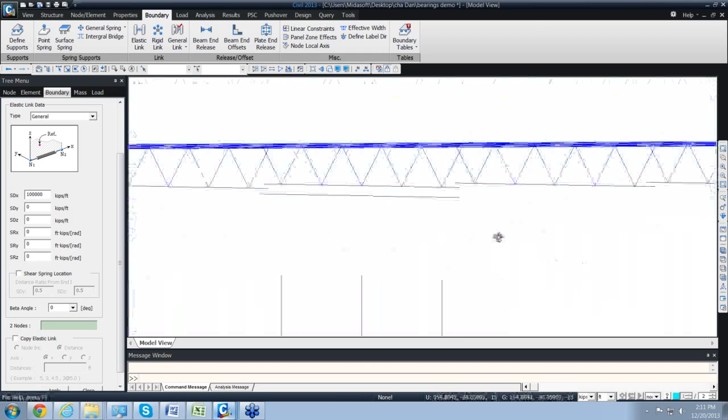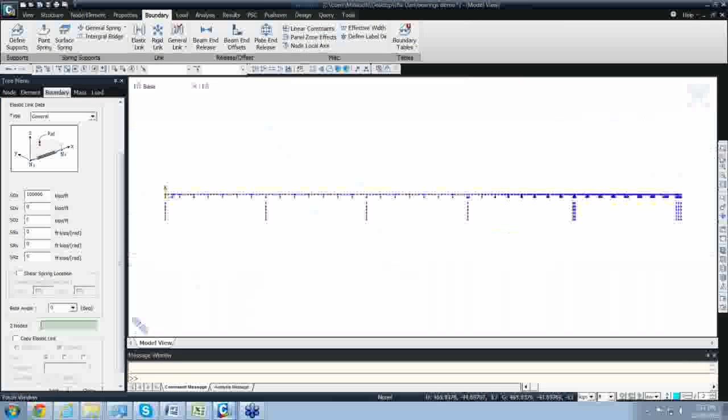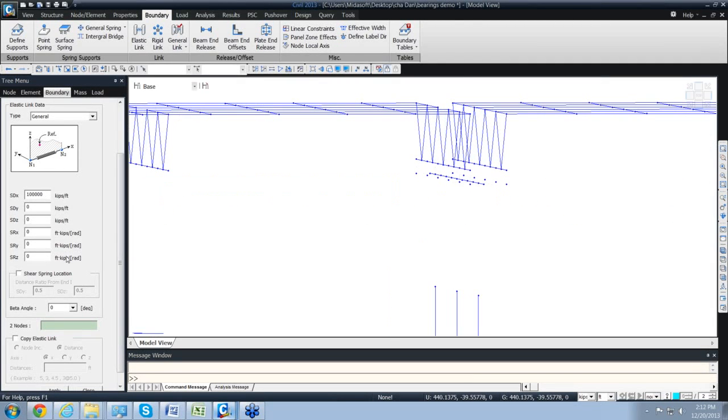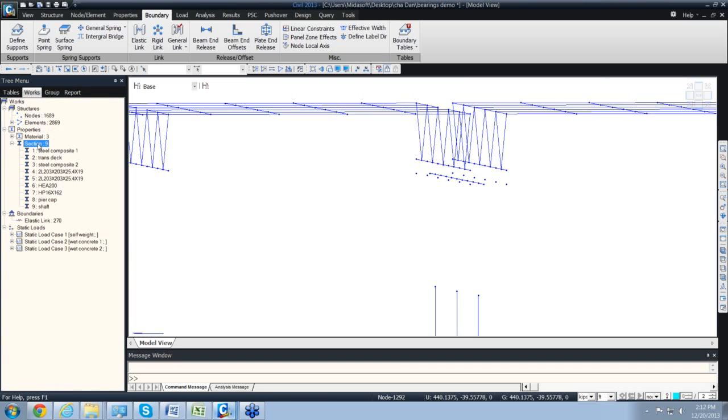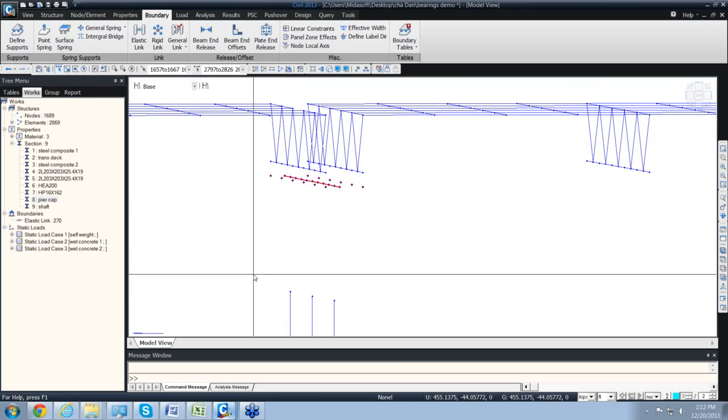Now there is one more thing. When I go to this location where you have the expansion joint, so what I've done is, this is the pier cap. Let me highlight the pier cap for you. So this is the pier cap here, and then I created additional nodes on the pier cap, and then I connected. So these nodes, let me just highlight those nodes for you. One question. The load from the superstructure gets transferred down through the rigid link of the cross frame down into the link that we just created. That's right. Yes, that's right.